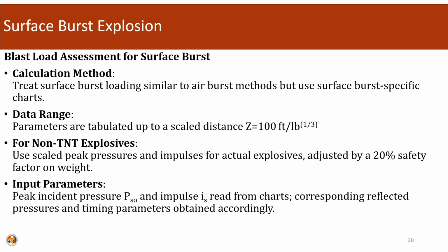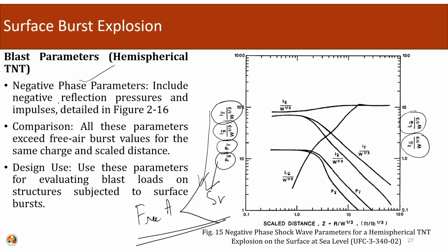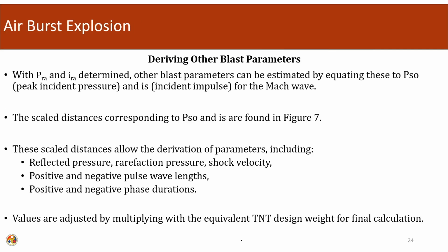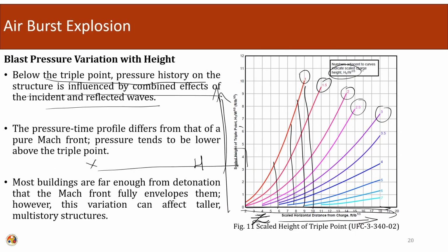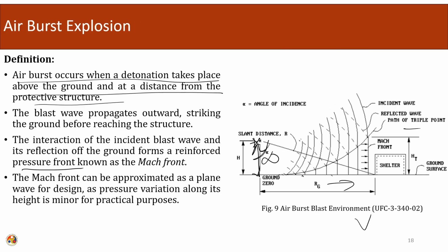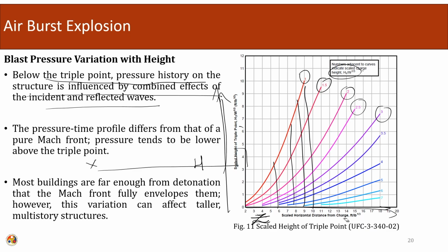So, blast load assessment for surface burst, calculation method. We will treat the surface burst loading similar to the air burst method, but use surface burst specific charts. The key thing here is the charts that we are using. If you look into all the charts, it is not always specifically written, but most of the time it will be written that this is for the air burst case.